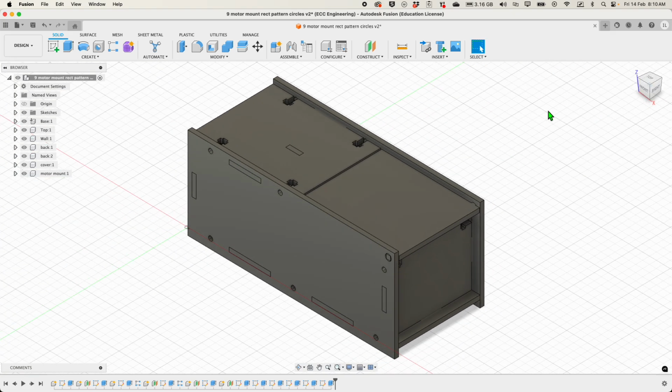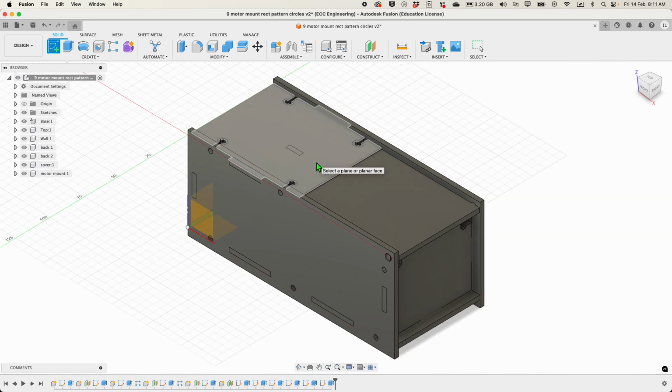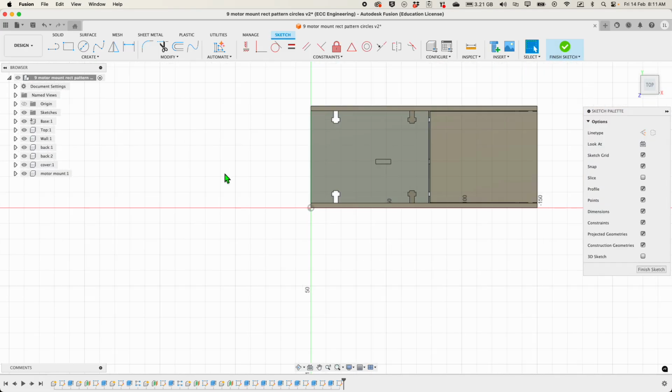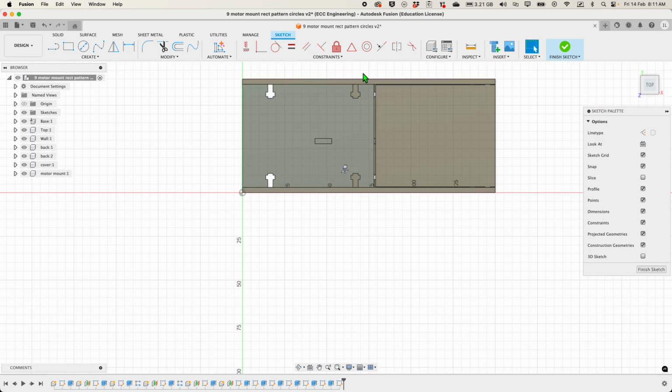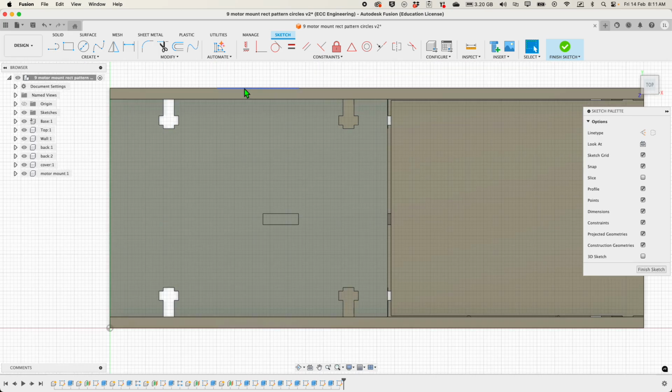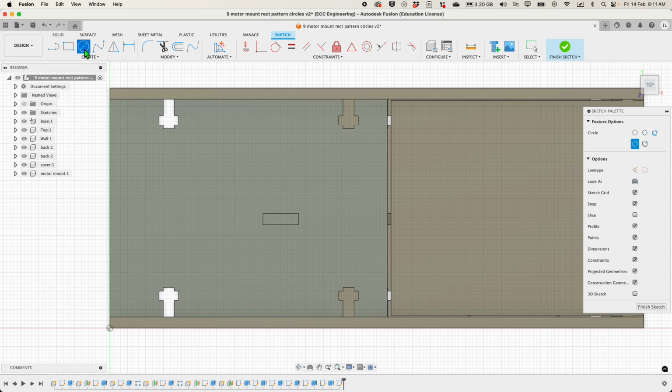Gonna hit home. All right, there's one more cut we have to make because we have to install a switch. Sorry, 2 more cuts. We've got to install a switch at the top here. And we also got to make one more cut for that captive nut at the bottom edge, right? So we're going to do the 2 cuts. All right, you guessed it, we're going to sketch right onto that panel, which is the top panel. And now the switches I'm using are the toggle switches, and I'm just going to create a circle, and we'll place it anywhere around here, and we will just dimension that in a bit.